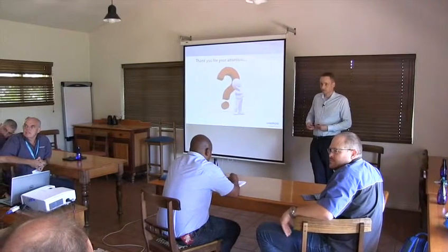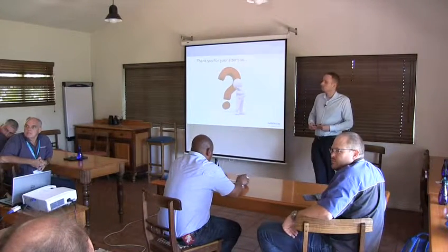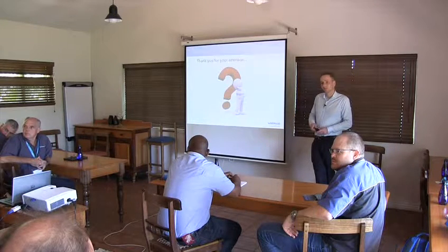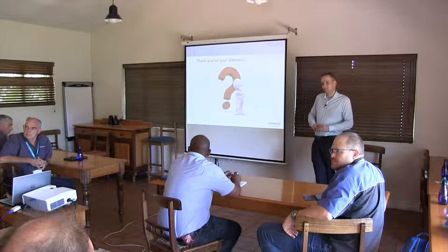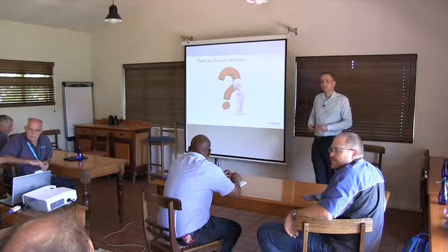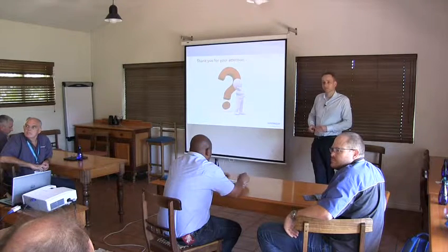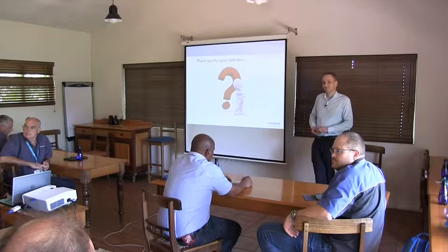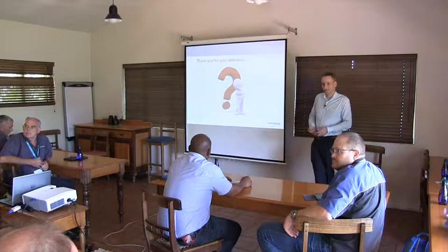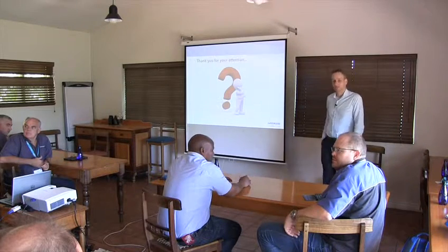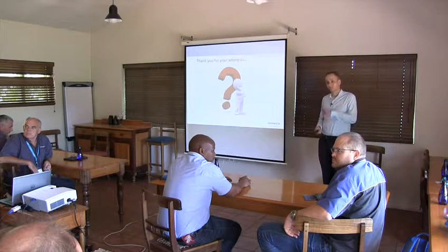What we picked up is that in Africa, people don't want to UV the stuff that's coming out of the tap. People want to UV the stuff that's coming out of the dam, the river, or the channel, or wherever they get the water from. And with the water scarcity that we have in South Africa now, it's becoming reused water. It might not be directly from a treatment plant, but it's mixed. So disinfection starts playing a bigger and bigger role.